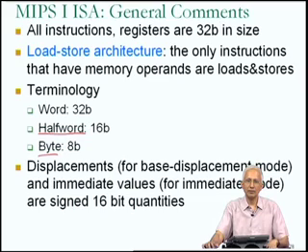Now, another important thing to note in the case of the MIPS1 instruction set is that we saw that the base displacement addressing mode is going to be used to specify the operands of load and store instructions. And we also saw that the arithmetic and logical instructions can have immediate operands. In addition, the load-store instructions have a displacement. Now, these values, the displacements and the immediate values, are going to be constants that are present inside the instruction. And therefore, we need to know how big those constants can be.